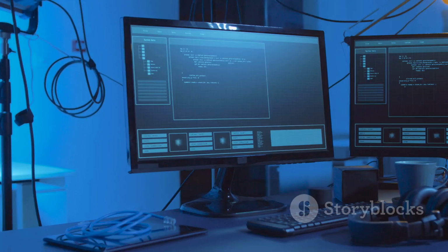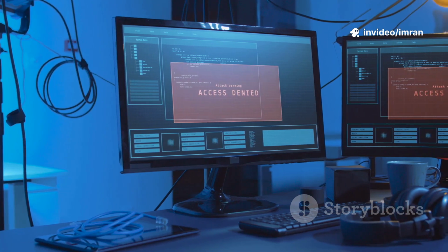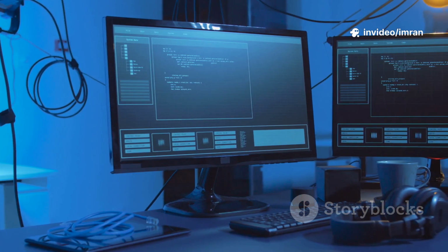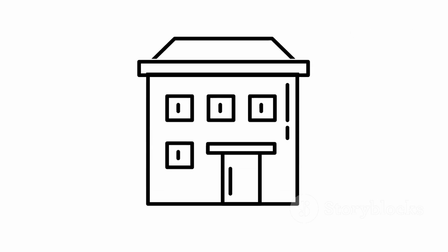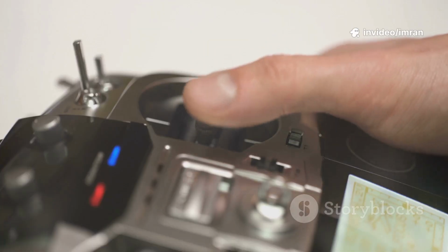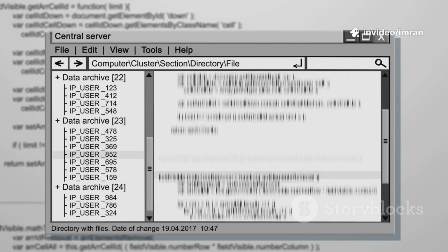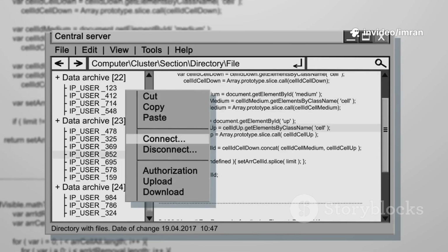Practice these actions. Let's explore the elements that provide information and control over your drawing environment. The status bar at the bottom features drafting aids and settings. These toggle switches help you draw with precision. Key tools include Grid Display, Ortho Mode, and Object Snaps. Object Snap, OSnap, allows your cursor to snap to geometric points.